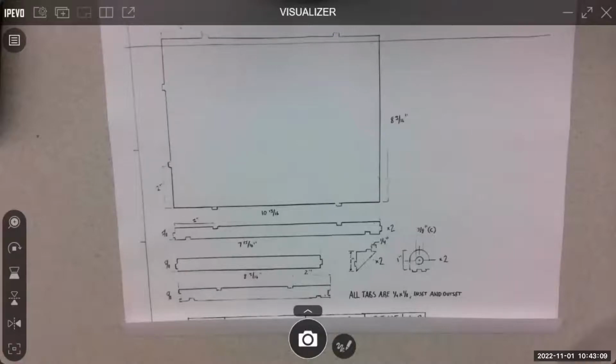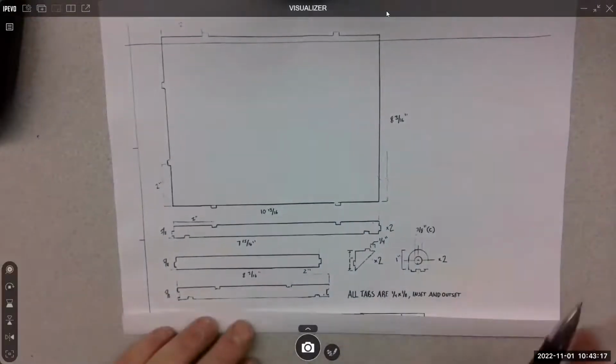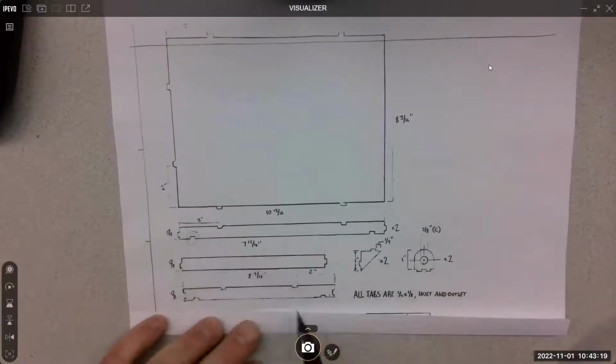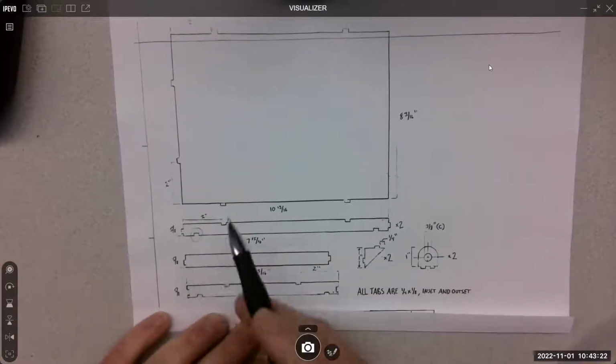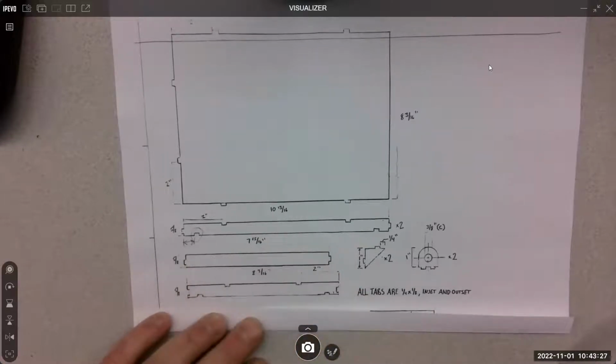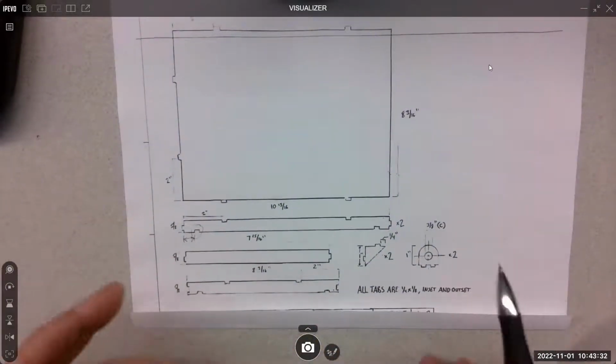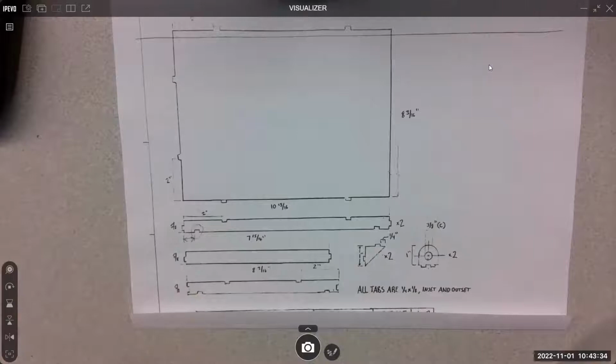And then try to just get all the dimensioning down on the drawing, because when I go to draw it, if I'm missing something, like for example, I don't know where that goes. So there's no dimension here for it, and I don't really see where it's going to line up to connect. So I can't even interpolate where I think it goes. It's easy to miss a dimension and forget one. It's really easy to do. So if that happens, I'll just send you an email or a note that says I'm missing a dimension.